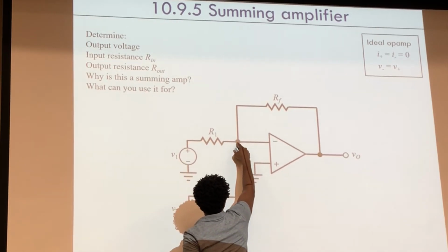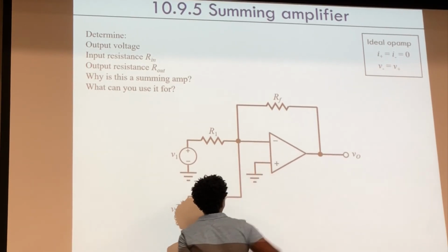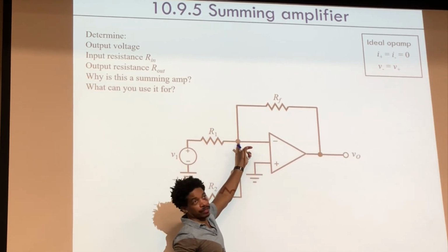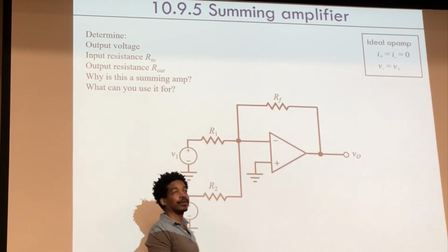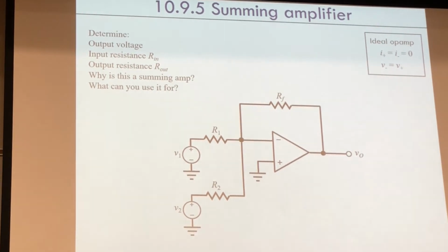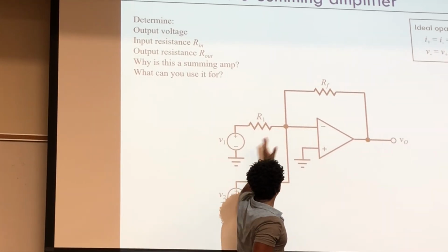The voltage here is copied from here, the non-inverting node. So it's grounded this particular time. I could have a source here. If that was 10 volts, that would be 10 volts. Okay, it just copied over. Once I have KCL, I plug in those values, and I'll have an equation that only has V out and VI, and I force it into a ratio, V out over VI. That's my gain.